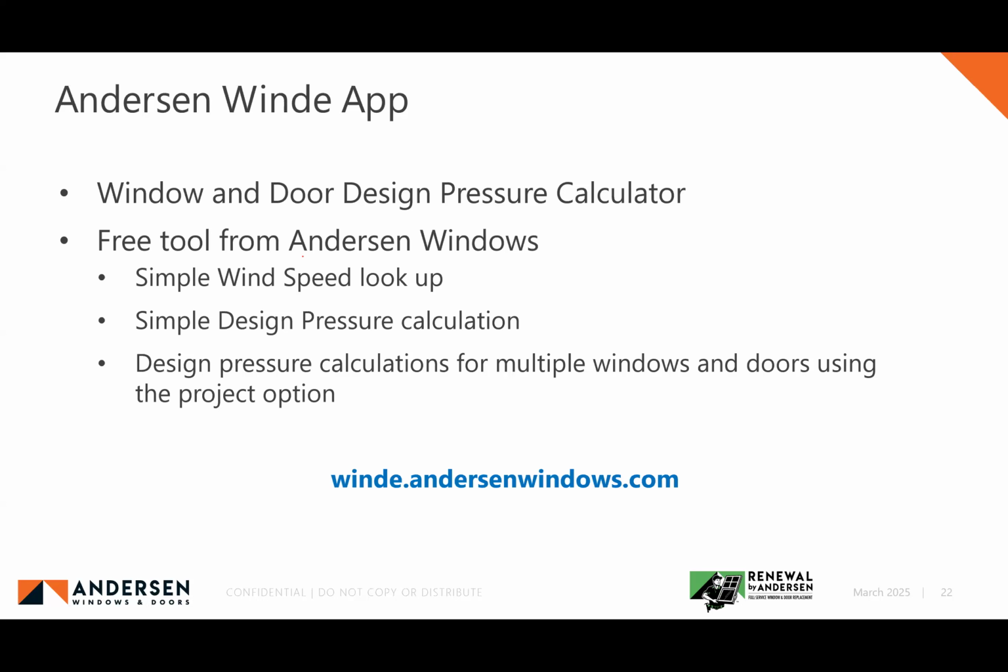Isn't there an ASCE app lookup by address? Yeah, okay, we're actually about to get into that. The question was, isn't there an ASCE app lookup by address? One thing I will point out, since you asked the question, all that ASCE app does is give you wind speed. It will not give you the design pressure, okay? And we're going to talk about that in just a few minutes, okay?